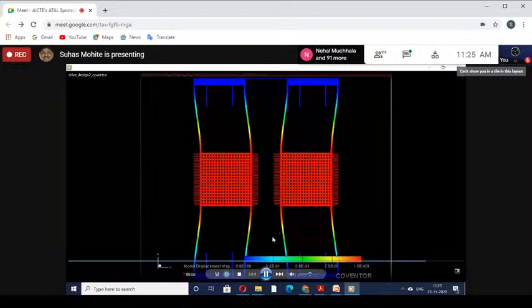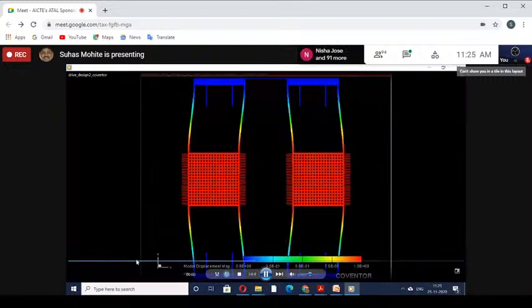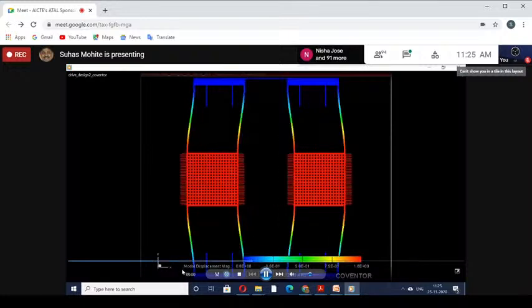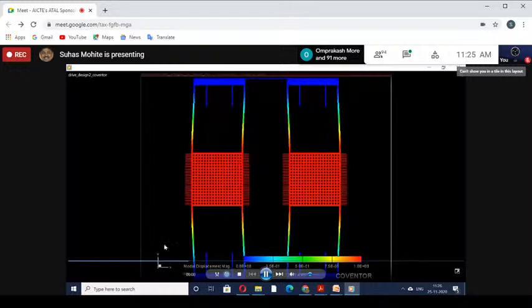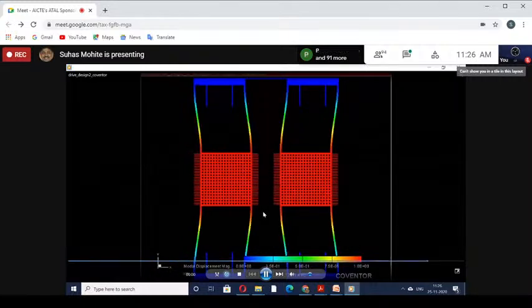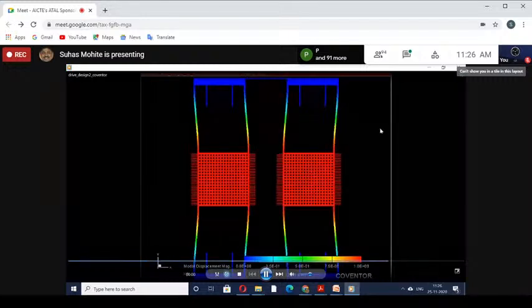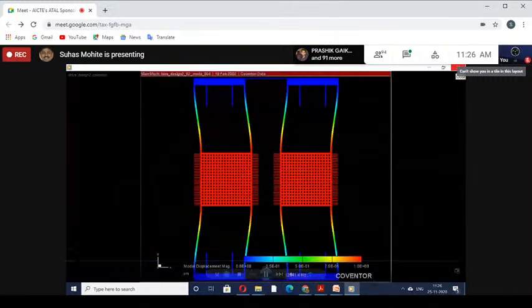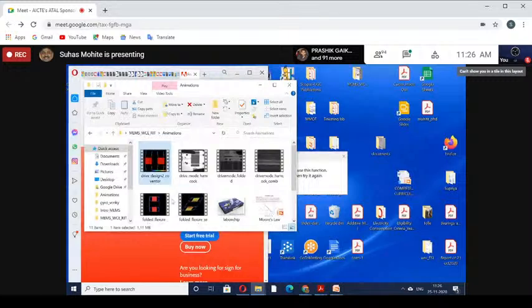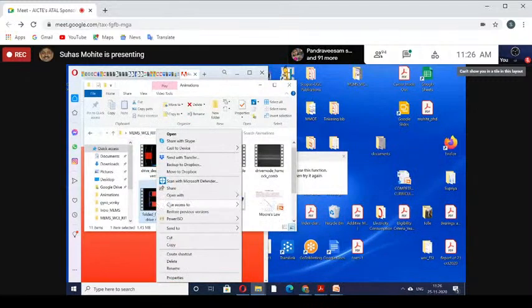And when this particular structure undergoes a rotation around a second axis, say the y-axis here, it is now oscillating along the x-axis. And when rotation is applied along the y-axis, in response to that, the Coriolis force makes it oscillate out of the plane in the z-axis. That I will demonstrate quickly, and then I will show you the actual device in the next minute.